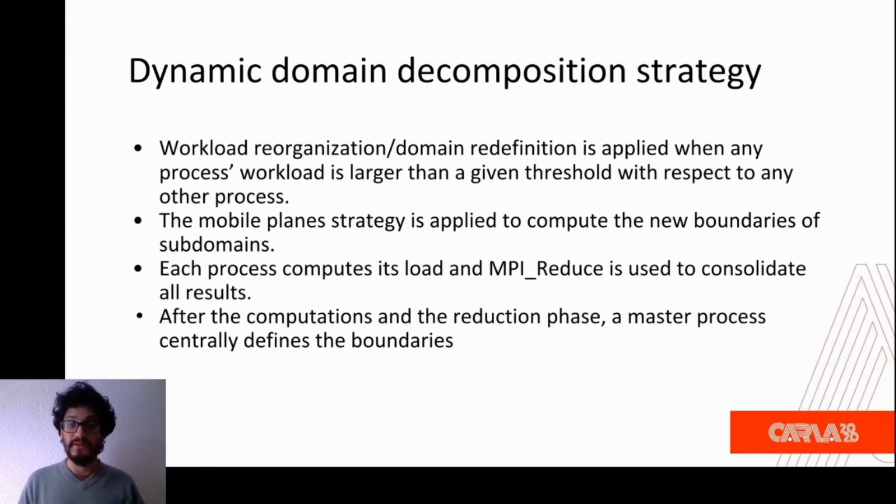The workload reorganization and rebalancing during the simulation is not applied on every iteration because it would be too heavy for the simulation. So it's applied only when a certain threshold is met. We empirically defined this threshold as when a given process has at least 20% more load than any other process in the simulation.